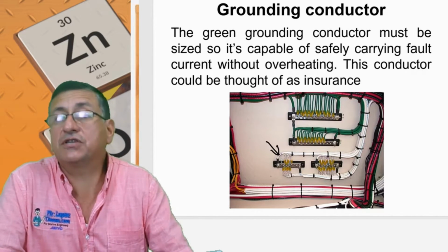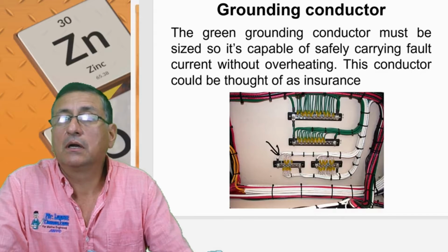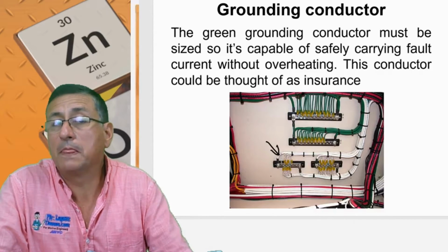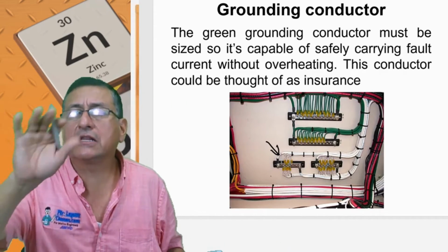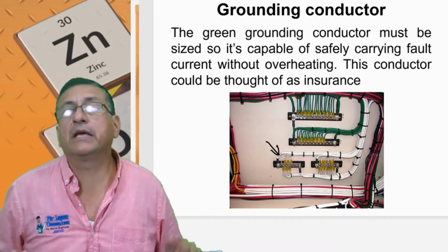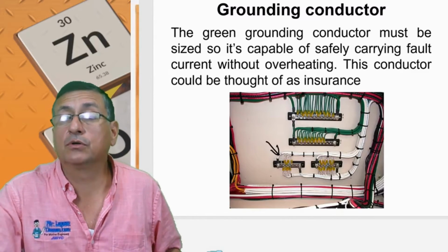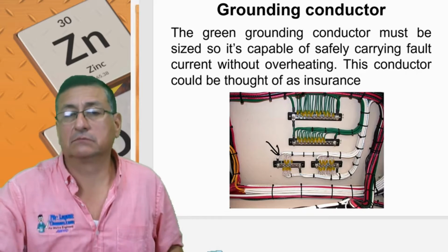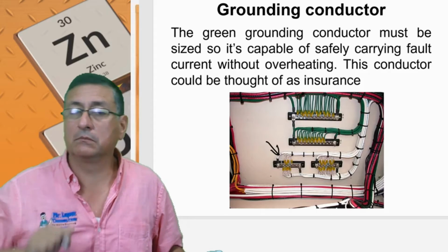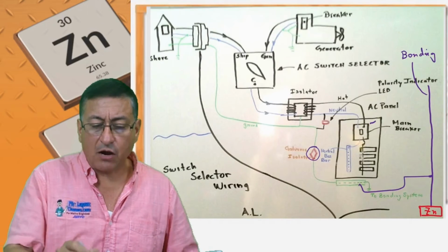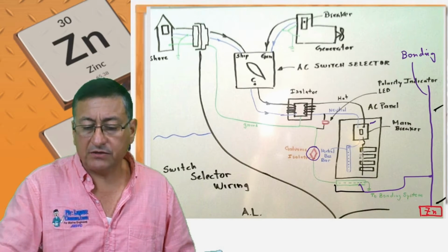A residential electrician did an installation a couple of weeks ago in my boat. And he connected the neutral and the ground, because in buildings it's not common, but it's frequently found, that connection. Neutral with ground, Mickey Mouse technicians. Now the ground is connected with the neutral in your boat, and your neutral is hot. Then your ground is hot, and your ground is connected with the bonding.